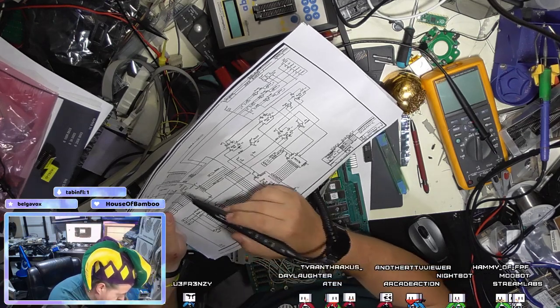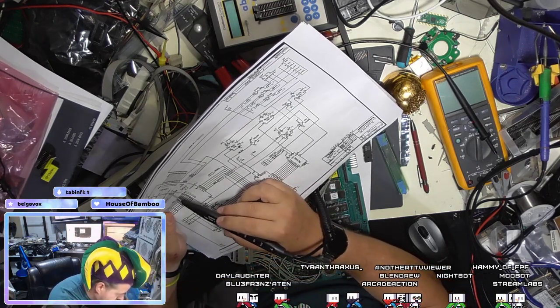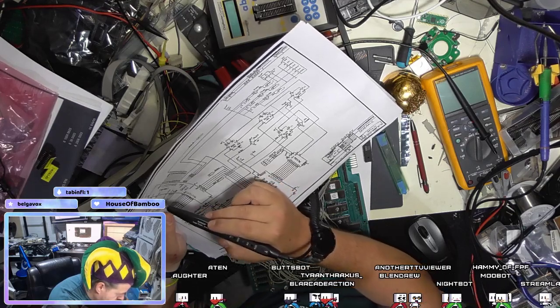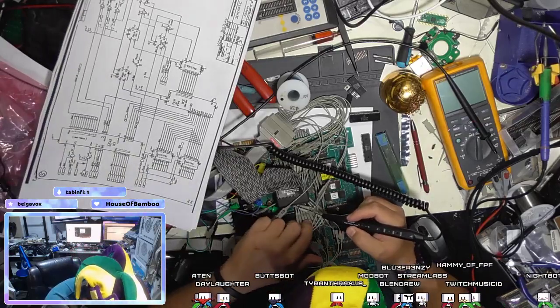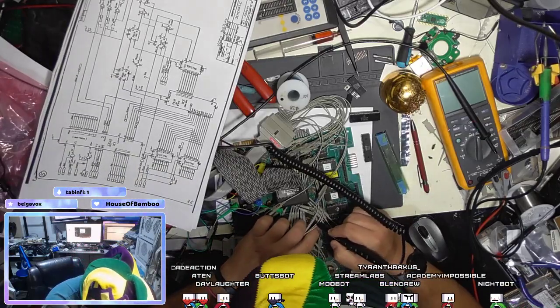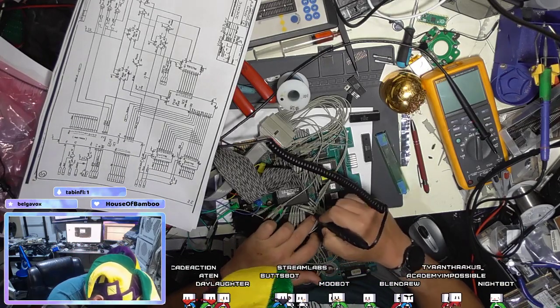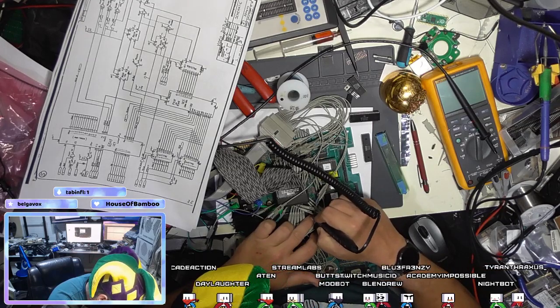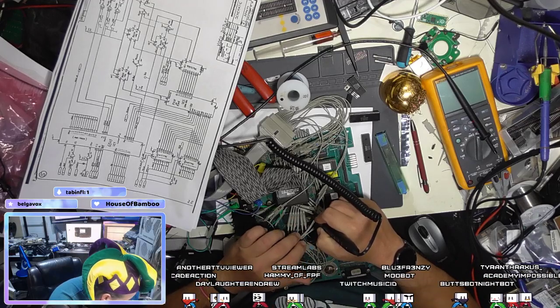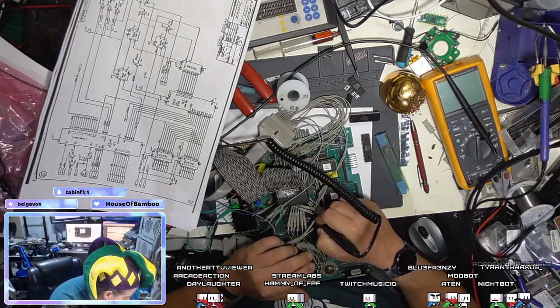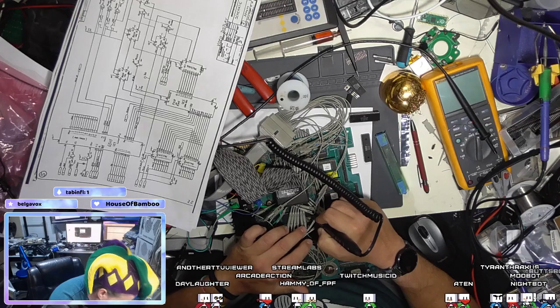So I'm just going to jump over here. I'm looking at 21, 22, 23, 24, and 25, and those are pretty easy to get to. Here's pin 20, that's 5 volts. 21. I got beeps, so that pin's actually doing something. That is the CRT clock signal.